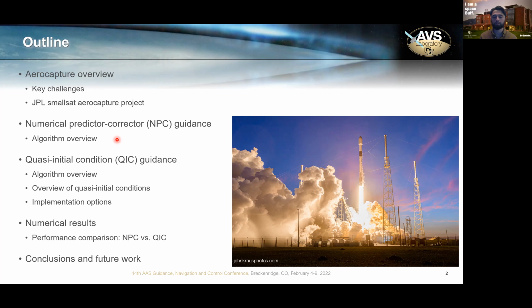So although it is arguably flight ready, Aerocapture has never been flown on an actual mission. And additionally, it requires autonomous guidance, navigation, and control in an uncertain environment. So because the delivery state, aerodynamic properties of the vehicle, and in particular, the density as a function of altitude in the atmosphere are all uncertain, and it's difficult to accurately model or predict the atmospheric environment, some sort of closed loop flight control is required to successfully perform Aerocapture using the aerodynamic lift and or drag on the vehicle